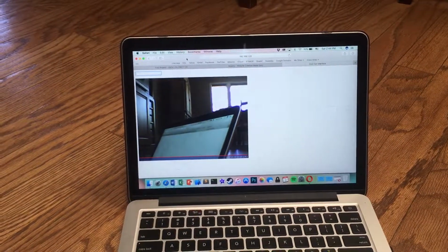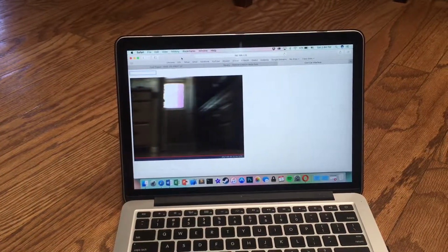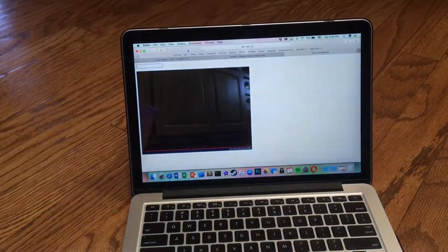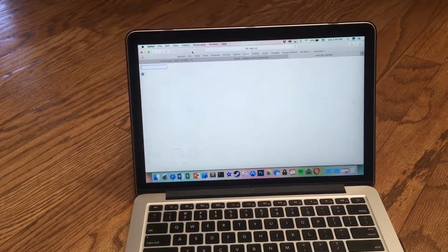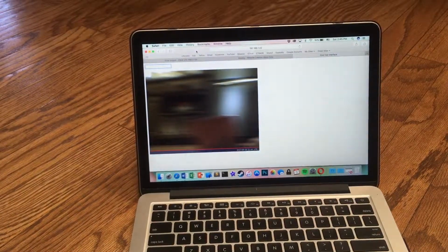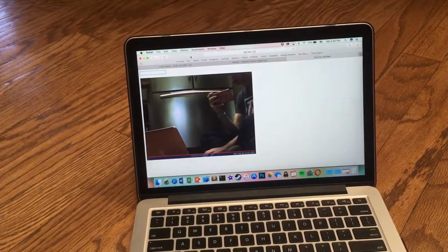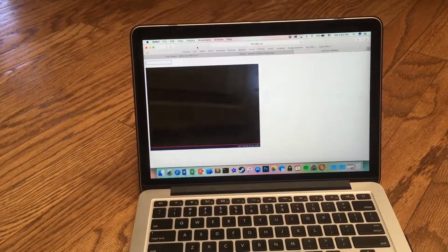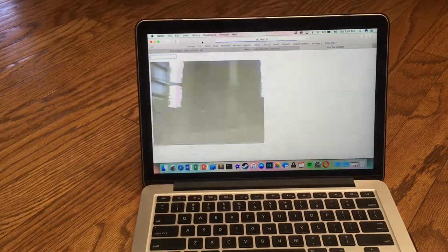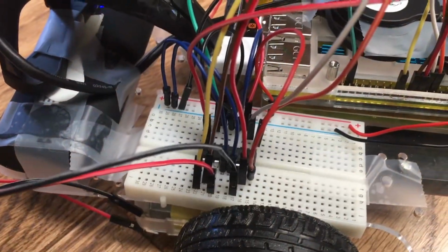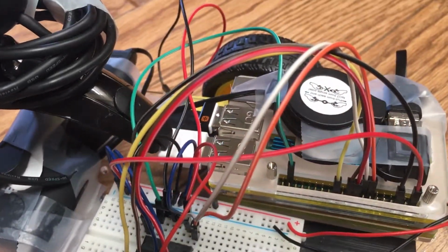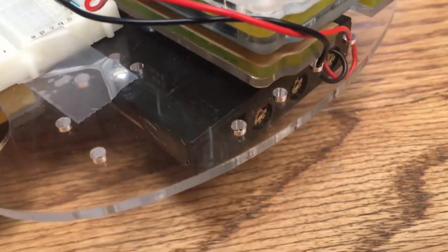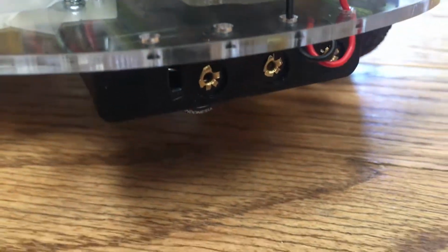Currently, all inputs and outputs on the RAMBO vehicle are based on the camera, Wi-Fi, wireless keyboard, and the onboard motors. All user inputs are single characters sent into the Raspberry Pi generated by keyboard presses. Alongside this, the USB webcam on the vehicle sends an input of 1 new image every 2 seconds. The first output from the vehicle is a set of binary GPIO pins on the Raspberry Pi. With every input, some of the pins will lose power while others gain some. The combination of on-off will tell you which motors to activate to move the vehicle.